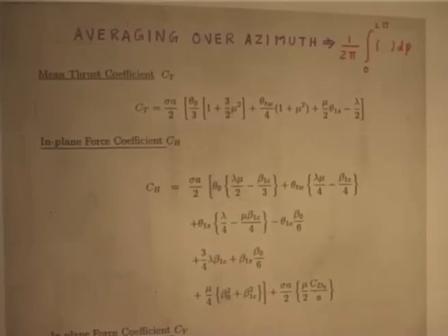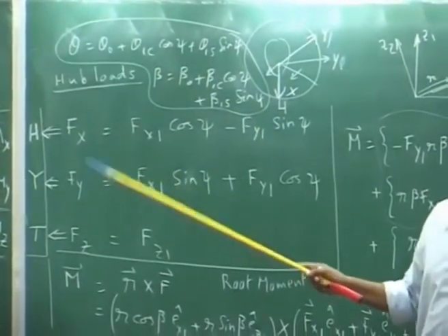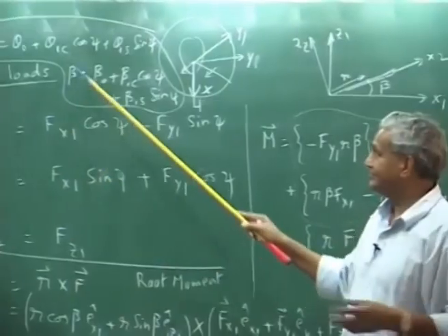So, you just multiply by the number of blades. That is what is done in getting the loads. Please understand there are several steps before you arrive at these expressions. It is not very simplistic like what we have done in hover, it is much more involved. But you made assumptions that you know these quantities, even though you do not know the number, you say, well, I assume that.